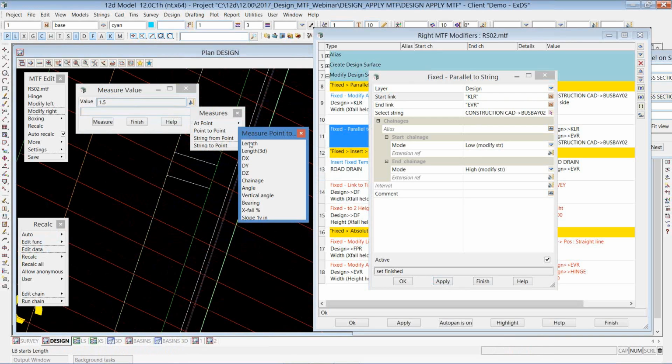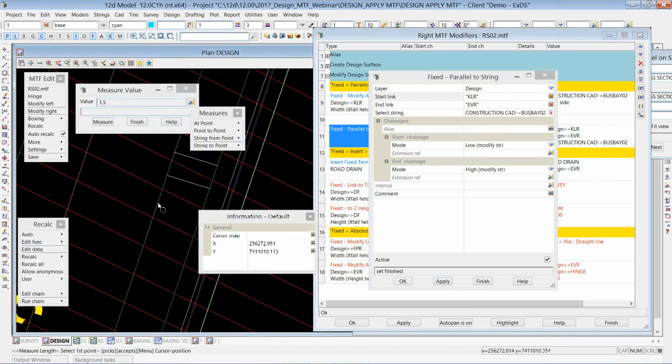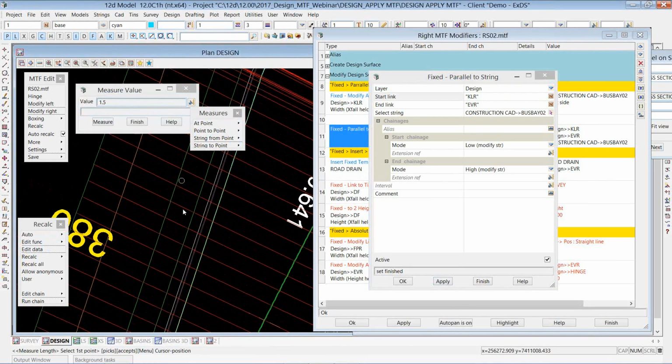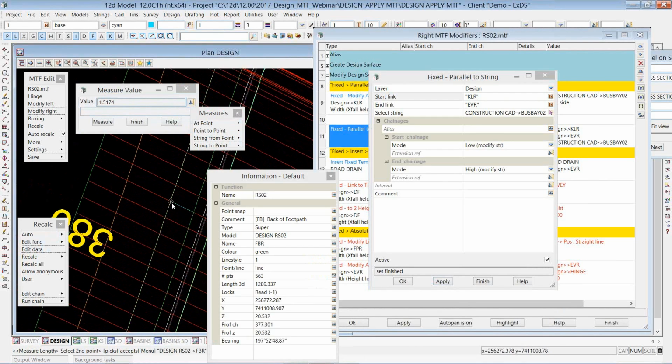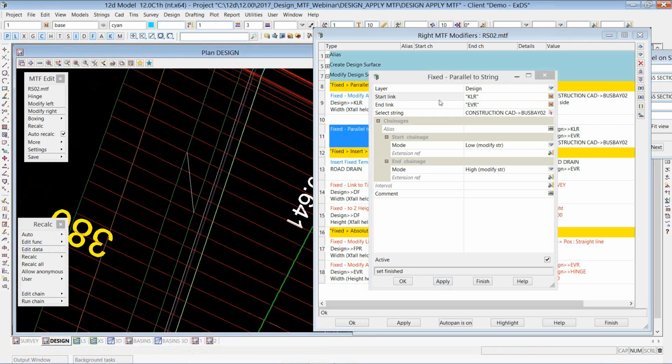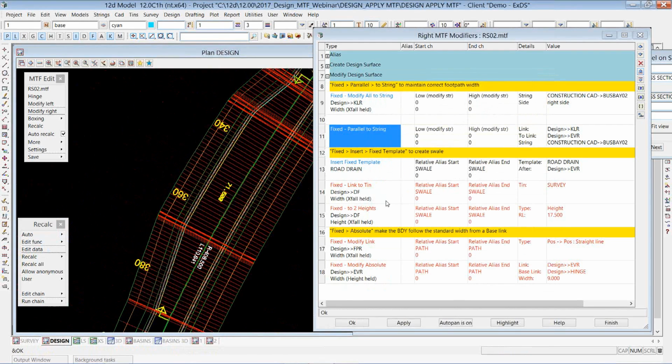You will have to be a little bit mindful of the cross sections you generate through this section of the taper, because obviously on the drawings, perpendicular to the cross section now, the width is obviously going to be longer, but it is holding the perpendicular or normal distance that you asked for in your template or your snippets, and holding the correct shape and width parallel to that string. So that's where we see that one being used a lot.